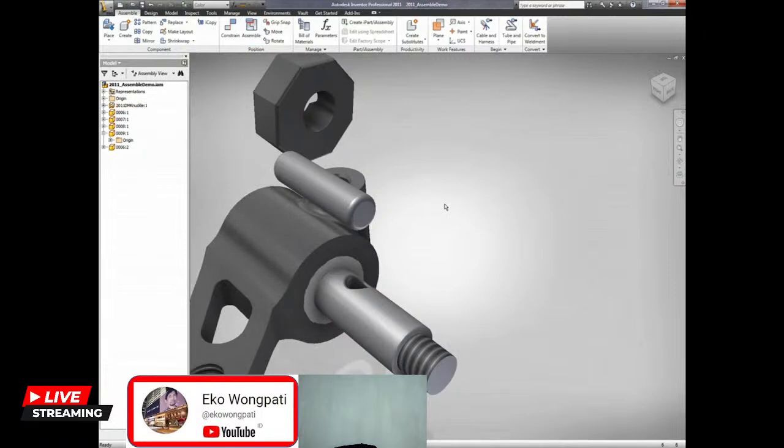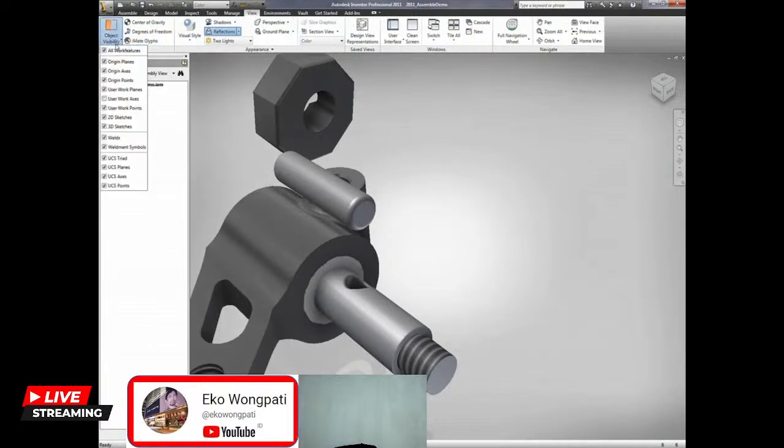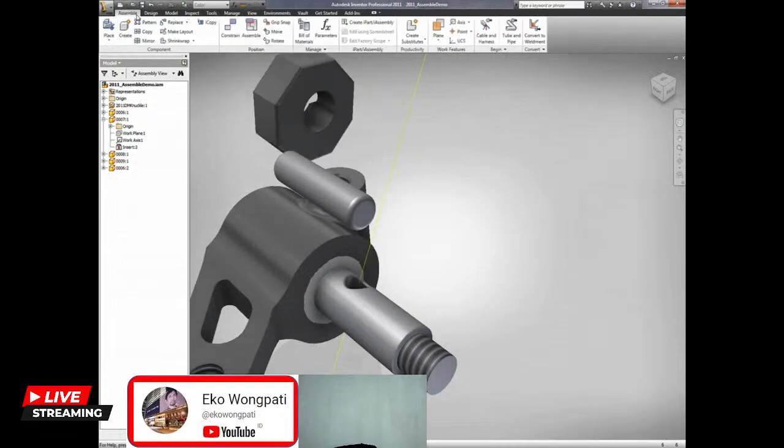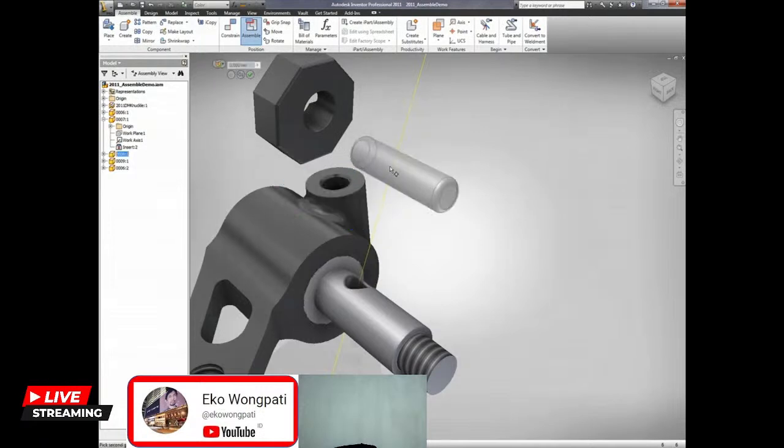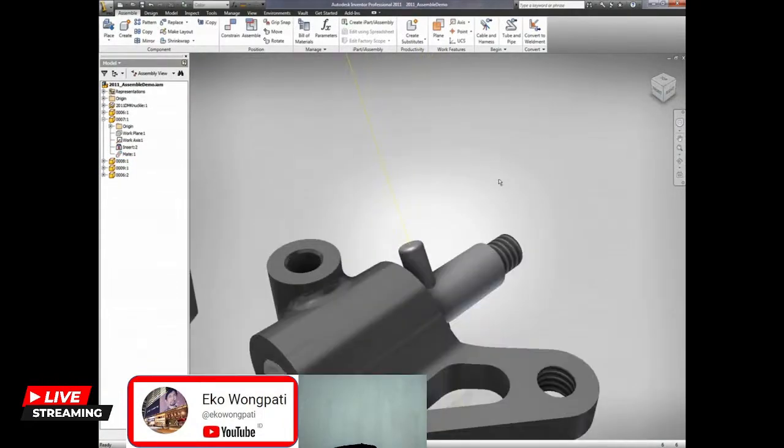So we simply grab our tool. We can make use of that tool by grabbing axis-to-axis mates, face-to-face mates, edge-to-edge mates, edge-to-face mates, a variety of different types of constraints that we can add within the interface. And it's as easy as a click of a button. We select which axis we want to align to and which axis we want to align from. Everything's completed. Now, the tool also has some intelligence built into it.